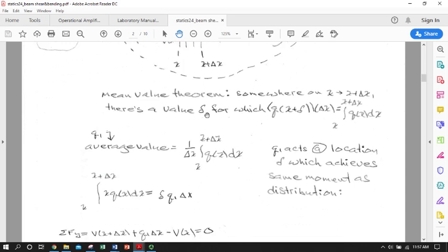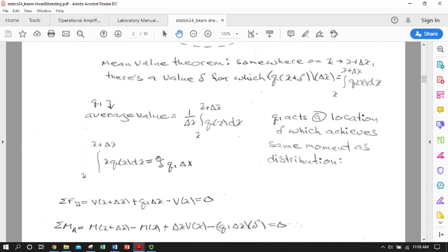That's kind of convenient. So we can pop those into the integral, define it at x and x plus delta x, take this, divide it over, and say that's effectively equal to the average value of the distributed load between x and delta x. It's another way of expressing that function. That allows us to say that this integral, which we've now included an expression for x in, this is now our moment.